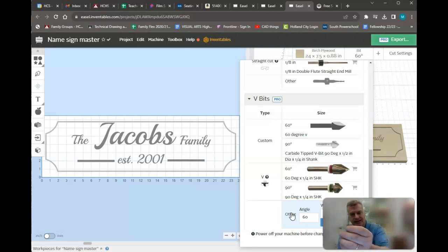This guy right here, this is a down cut, 1/4 inch down cut bit. That's another one that you guys will probably be using fairly regularly. And this one is an 1/8 of an inch down cut bit. This one's really, really useful. The only thing is that it will snap off fairly easily, which is bad, obviously. So you got to be a little bit careful with these. They do make 1/16 inch in diameter down cut bits. I have not bought any. I have not tried any, because I've snapped quite a few 1/8 inch down cut bits, there's no way I'm going to use a 16th, because I would just probably snap it really, really easily.